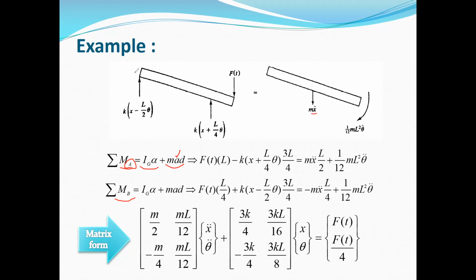So the moment about this point A is equal to Ft multiplied by its arm, which is this length, and it's equal to L. And also this force multiplied by its arm, which is equal to 3L over 4.